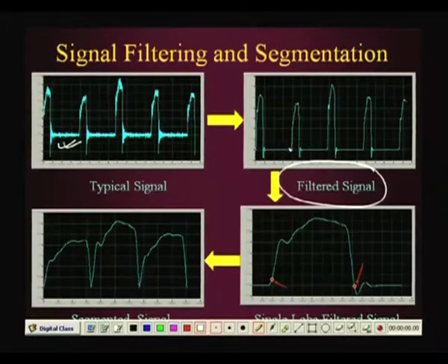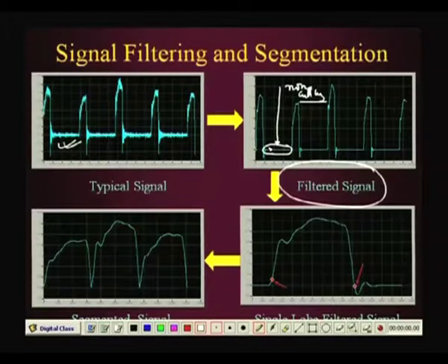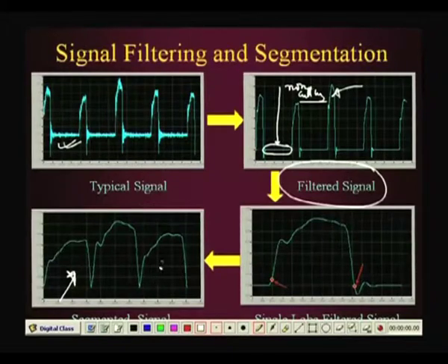Next, we notice that these are the parts which are non-cutting, so these parts do not keep any information. The parts which keep information about the status of the tool are the cutting parts. So, we first remove the non-cutting parts, and then we get what we call the segmented signals. Now that is a collection of lobes. So, these are the lobes.